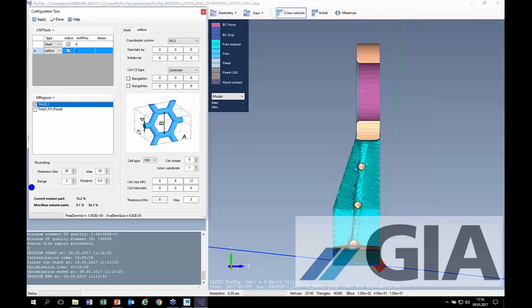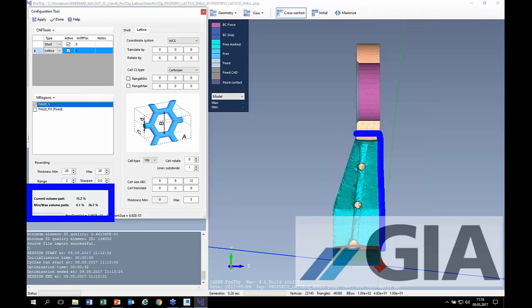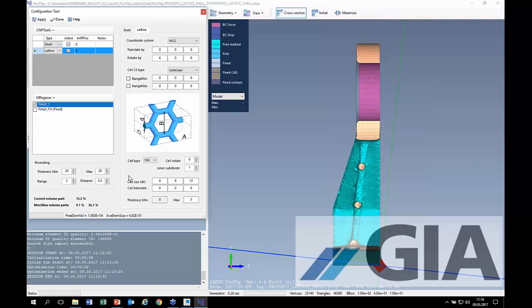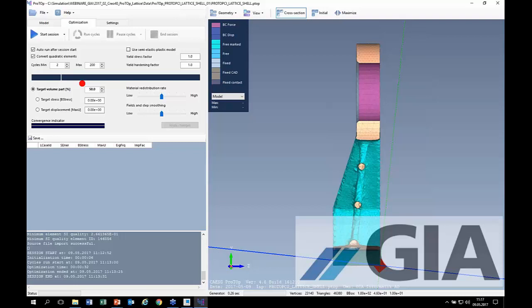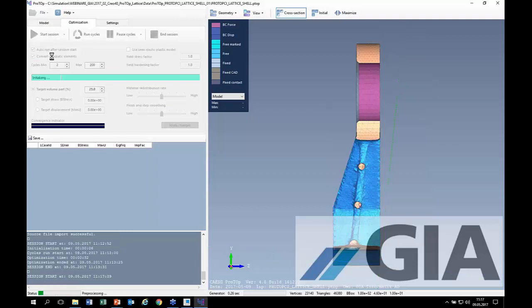And we can see right now here, okay, with this configuration, we are getting here on, let's say, that area which can be modified. We can change our volume or our mass between 0 and 37%. So that means later on for me, if I'd like to optimize my component in that area, it makes sense to type in a value between 0 and 37%.